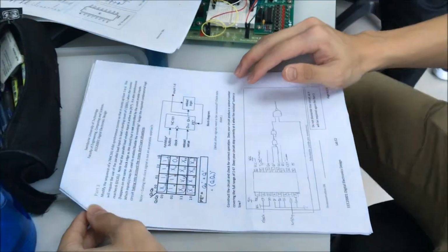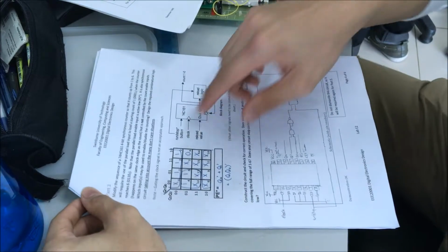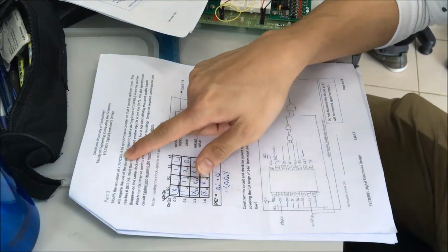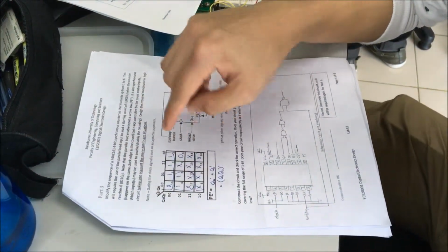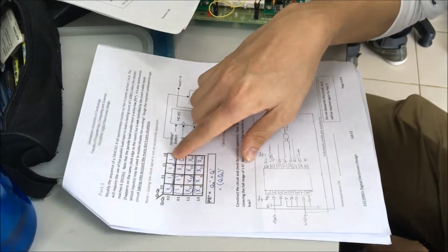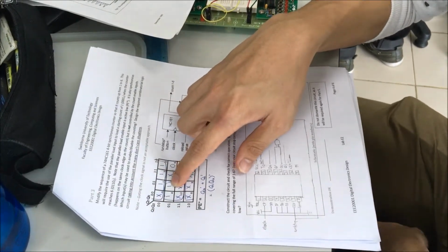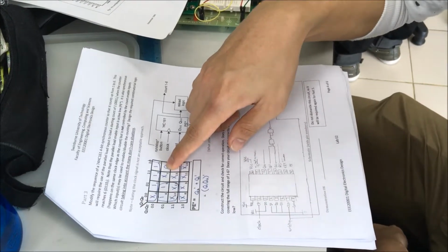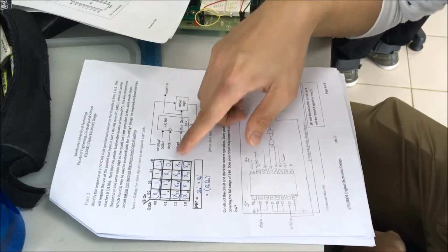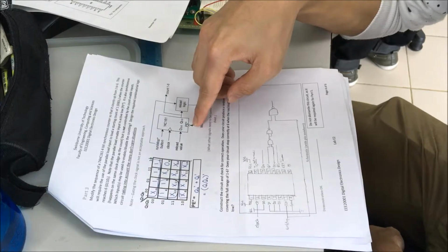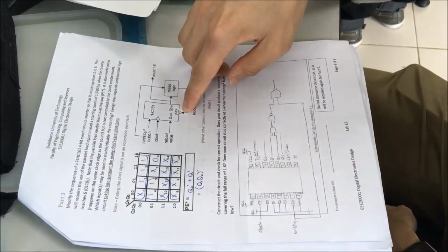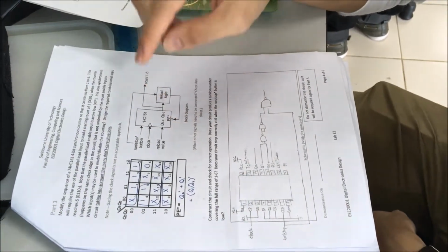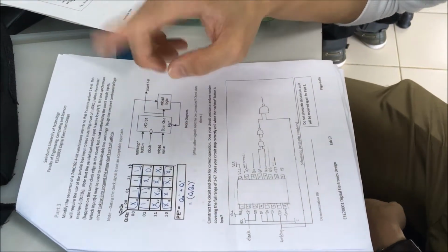So here, we are going to design a circuit with IC 74HC161. We're going to count 1 to 6. So here we have 1, 2, 3, 4, 5 with output 1, and 6 with output 0. Because with the output 0, it is going to activate the PE, and since the PE is active low, it will give an output of 1.